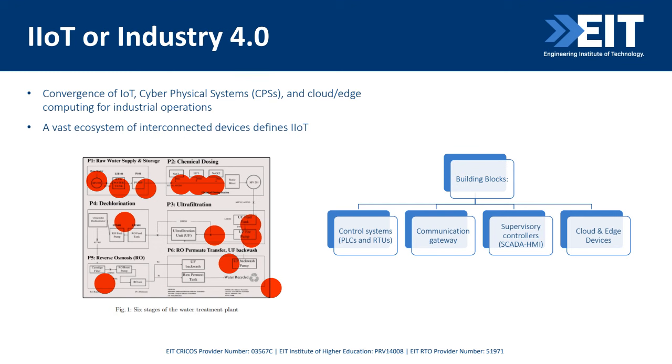But we can introduce electrical engineering. We can introduce devices such as a programmable logic controller, which automatically is able to open or shut a valve, or is able to control the pressure with which the water is flowing, and is able to transmit it to a unit in digital format, which is ones and zeros. So that is subsequently processed, and you can take decisions based on those numbers. So this is digitization to the right, and this is operations technology to the left.